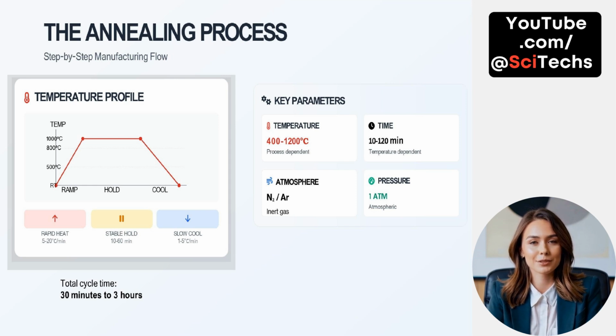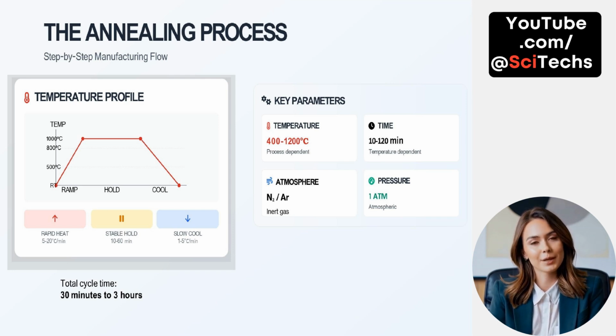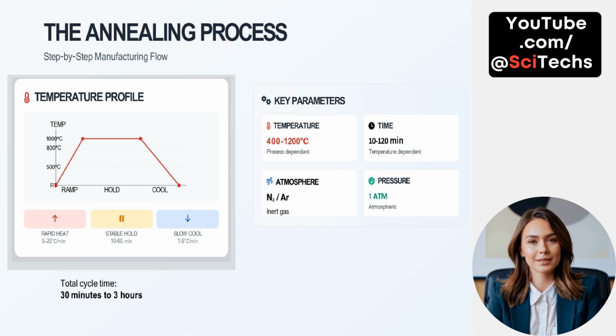The atmosphere within the furnace must be controlled using inert gases like nitrogen, N2, or argon, Ar, to prevent oxidation or contamination during the high-temperature hold. Pressure is usually maintained at 1 atmosphere or ambient pressure, which simplifies system design and avoids additional stress on wafers. Overall, the total cycle time, including ramp-up, hold, and cooling, can range from 30 minutes to 3 hours, depending on the specific process and wafer requirements.